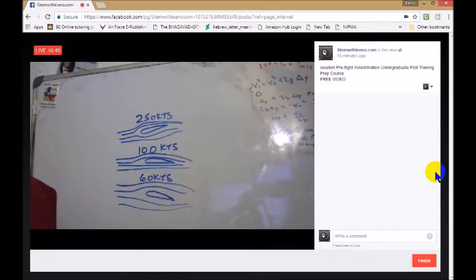All right. So we talked about the 4 forces of flight. And we talked about drag and how drag has subcomponents. We talked about parasite drag. We talked about induced drag. Induced drag is just the generation of lift. That's how induced drag is caused.